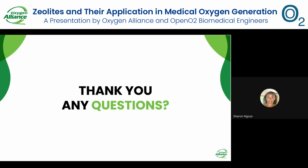Sharon: To add on what my colleague has said, zeolite does have a lifespan. Some searches have said that it can last up to 60,000 hours, but sometimes it has to function less than that. For example, if there has been moisture contamination. If the moisture contamination has happened before those 60,000 hours, it means that it has to be changed.